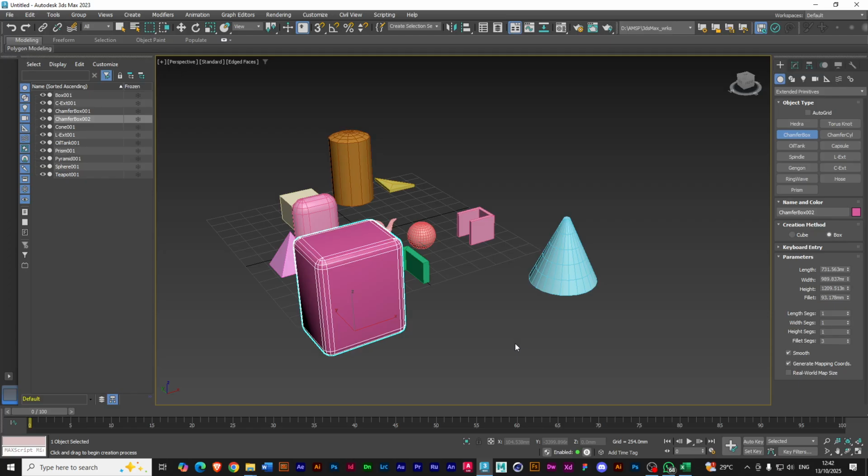So subdiv is for sculpting. If you want to sculpt, you need a lot of faces because you need a lot of segments to define the object. If it doesn't have a lot of divisions, your sculpt won't come out well. Then volume modeling is like using gas to create a solid object, gaseous-like stuff. It actually uses the concept of booleans.